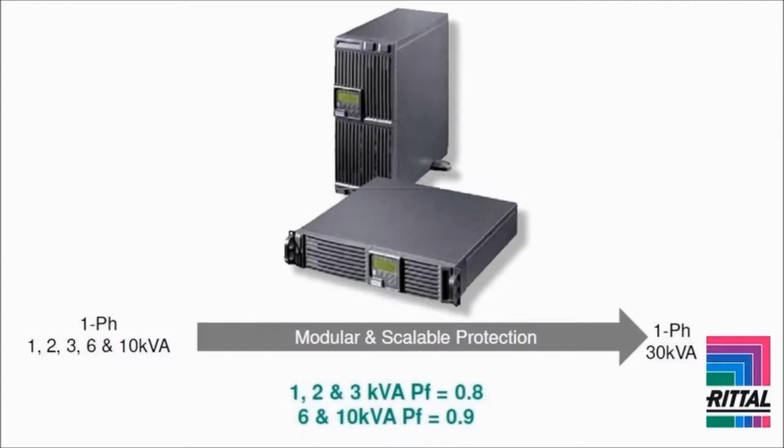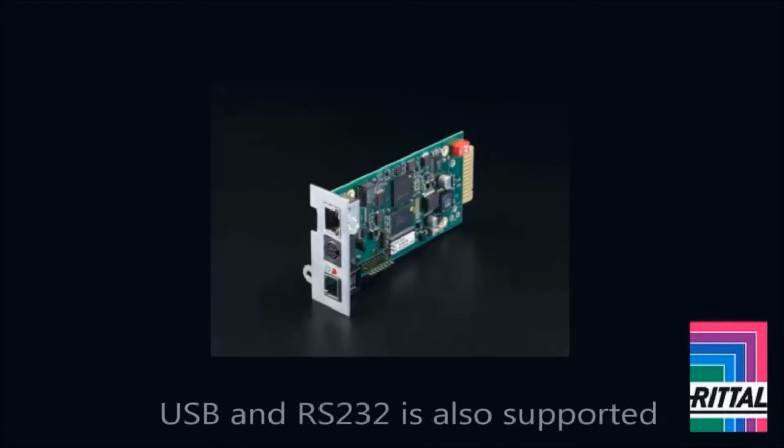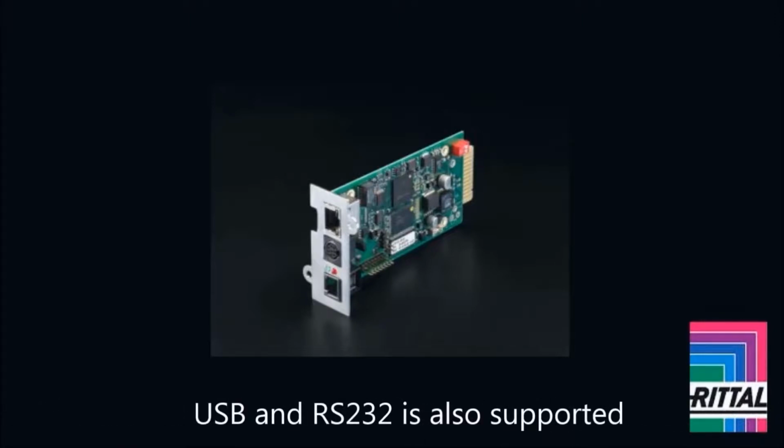The flexible design of the PMC-12 allows scalability from 1 kVA UPS to 30 kVA UPS just by adding modules. The 6 and 10 kVA units can also be paralleled for N+1 configuration. The PMC-12 comes with a card slot, configured to accommodate an optional SNMP or relay card. The PMC-12 also supports USB and RS-232.